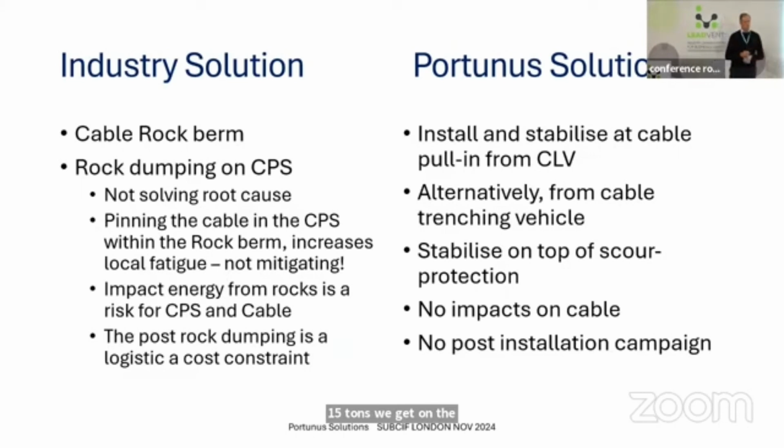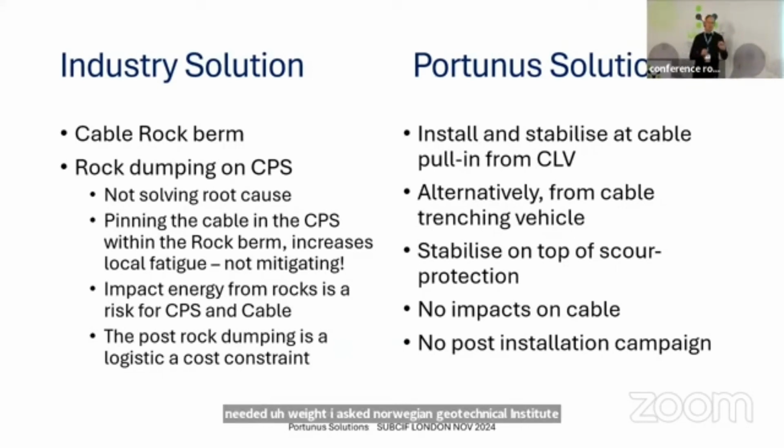So if we wanted that CPS system to stay put, we needed a weight. I asked the Norwegian Geotechnical Institute, and we need seven tons of weight in water to keep it relatively stable, 10 tons if we want it fully stabilized. Can we handle that from a cable lay vessel? We found out, no way, we cannot handle that in a lay trajectory from a cable lay vessel. The project was dead.